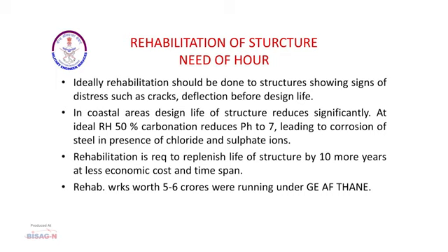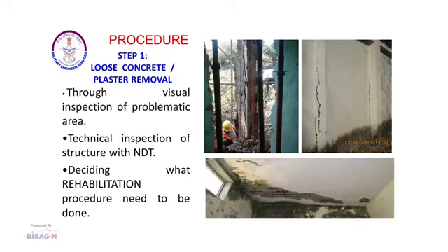At Air Force Station Thane, we had works of about 5 to 6 crores of this nature, from which we gained this experience. So, we go through the procedure: what will be the steps to carry out rehabilitation of a structure. First step, loose concrete or plaster removal.